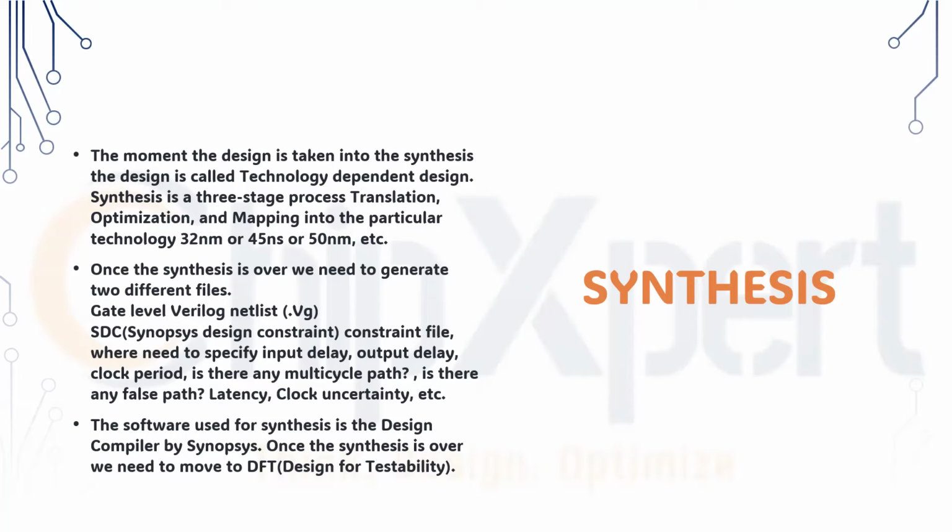The fabrication units will provide a technology file, like a standard for each of the gates. A CMOS should be like this for a NOT gate, an AND gate, or adders, flops. All this is mentioned in the technology file only. It is like a reference mapping. This NAND gate will again be defined in the technology file in a physical format, and that will be used by synthesis to synthesize in a proper way.